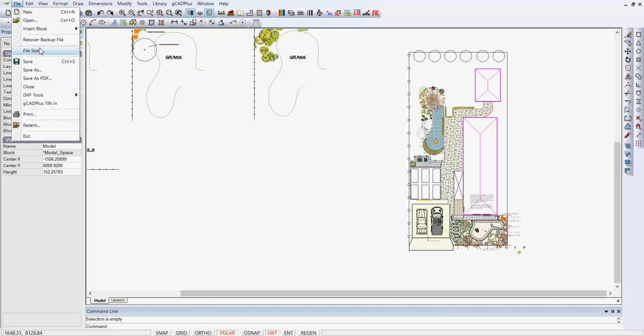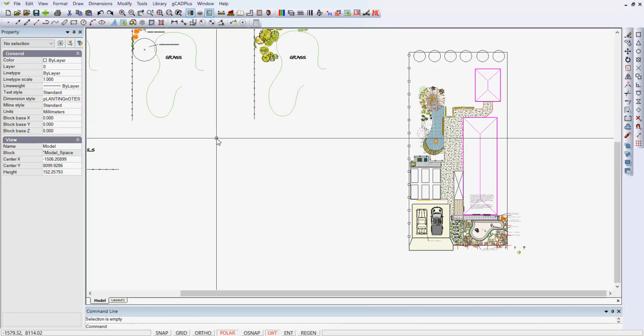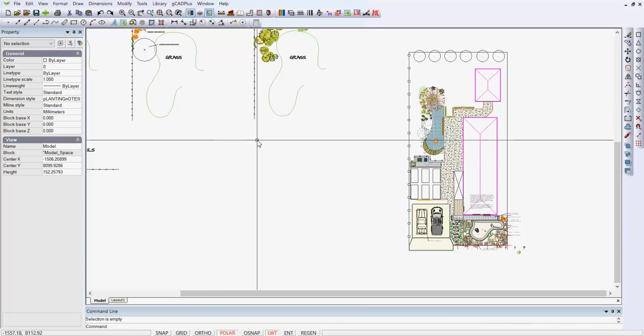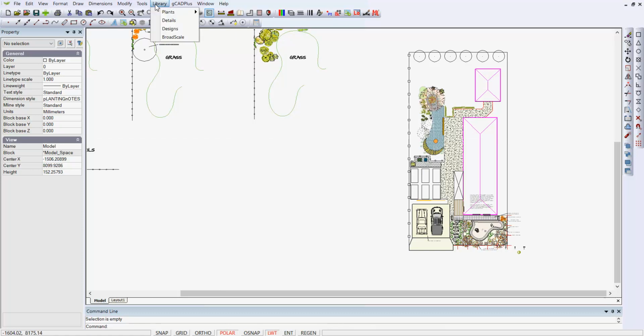You have to use File, Save as a PDF, and that has some limitations in that it is sometimes difficult to get an acceptable resolution, whereas a print to a PDF writer will give you very high resolution, but we've not been able to find a PDF writer yet that will print transparency. So that's a brief overview of some of the symbols and symbol sets that are in this group.